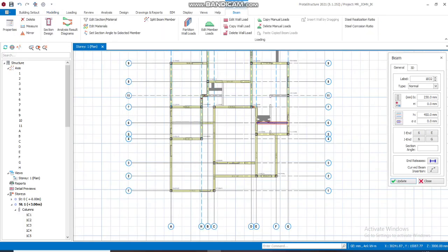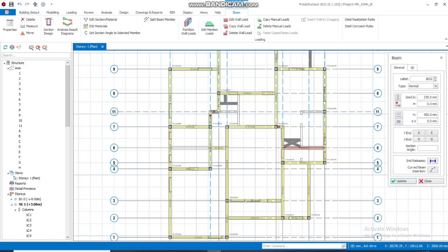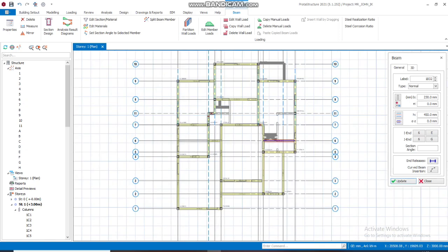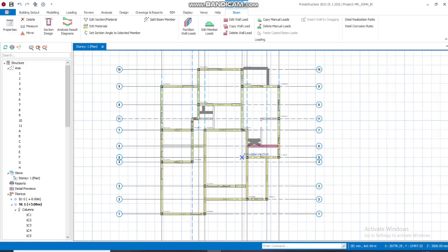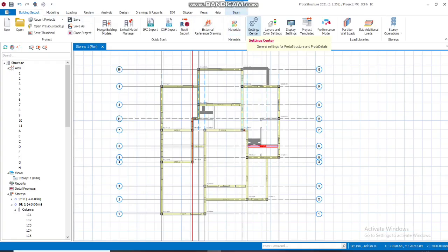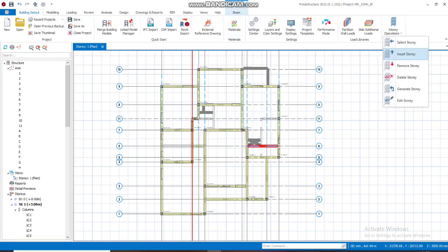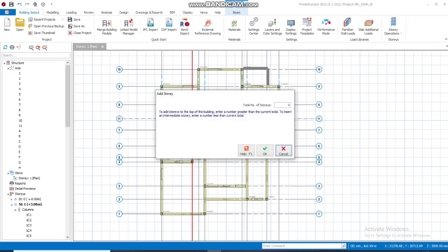So you ensure your axial line passes all the places that your beams are going to pass through. At all your panels, all the sides that your panels are going to pass, you ensure that there's an axial line there, else you will not be able to put your structural element.